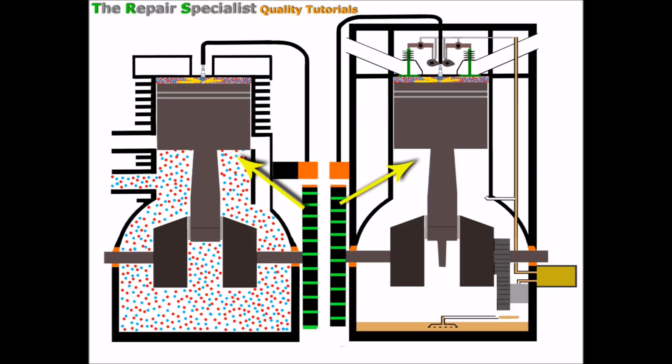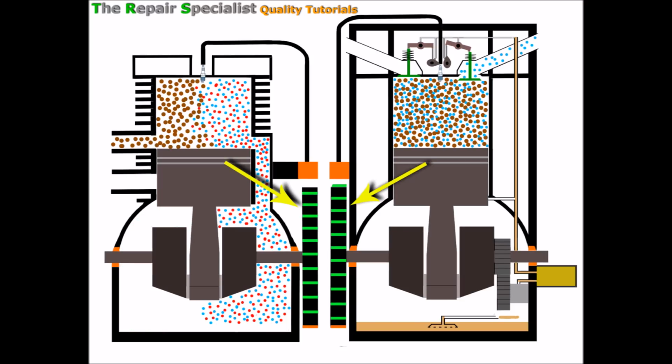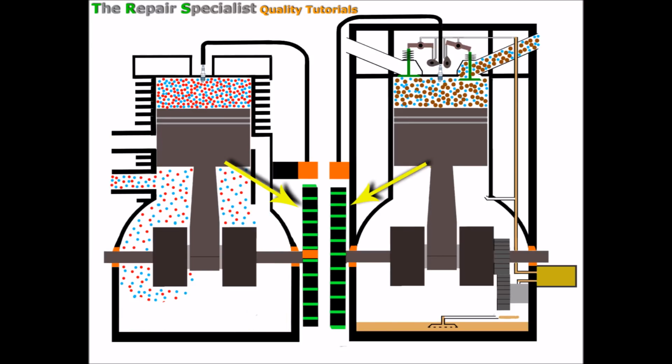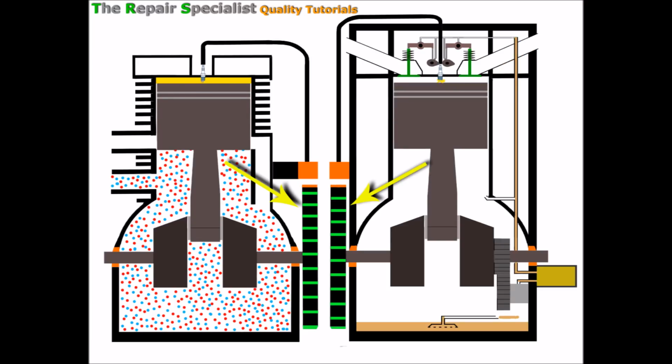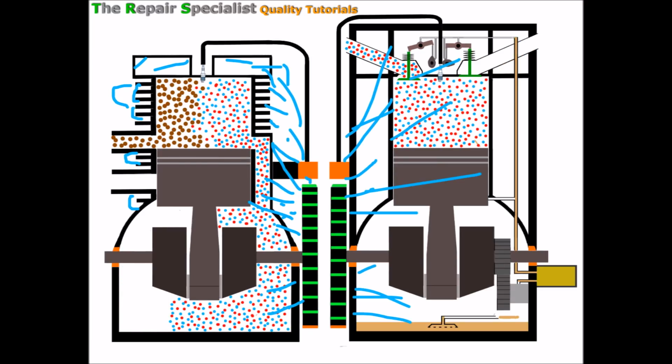And that first brings me to the flywheels. Earlier on, I emphasised these green areas, what are called the vanes on the flywheels. They're more specifically referred to as air vanes, and as the flywheel turns, so as the engine's running and the flywheel's turning, them air vanes are protruding out from the flywheel and they're generating an airflow. And on these type of engines, known as air-cooled engines, all the air is flowing around the engine and just taking away the heat. So it's generating an airflow with the environment past the engine and out to the environment again. So it's bringing air, cool air in from the environment,